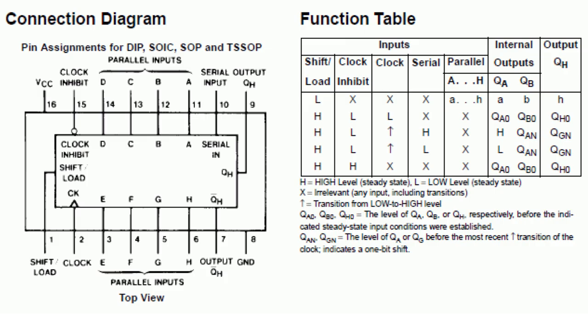And here's another shift register. This one's got the serial in. It's got parallel out. It's got a clock in, and it's got a shift or load. And you can go in either direction. It's sort of an interesting way to go. If you have a basic shift register, all you really need is your serial input and a clock, and you can take in the data.